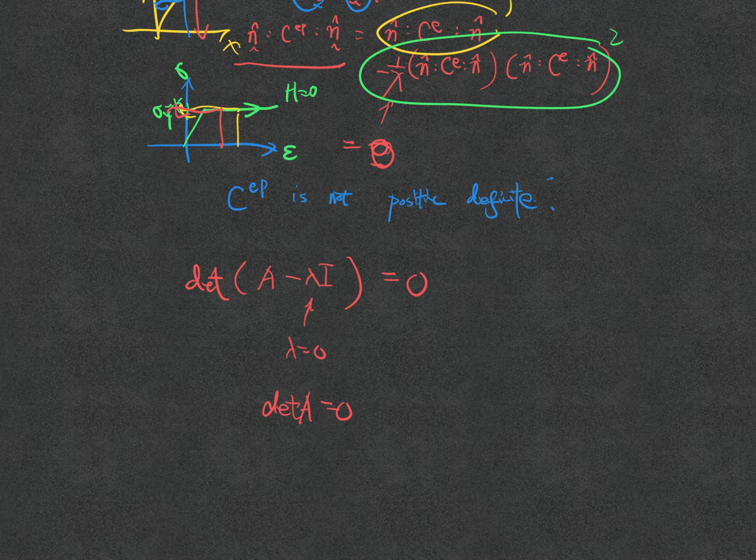Okay, so this is actually why, with the perfect plasticity model, if you put it into the eigenvalue solver in the computer, you won't actually get the perfect plasticity. Why is that? Because the computer doesn't really store the zero unless you model it as an integer. You will have some floating number, you will have some tolerance, and then it will flip-flop, but it doesn't matter. So it would usually lead to a C^ep that is not stable.